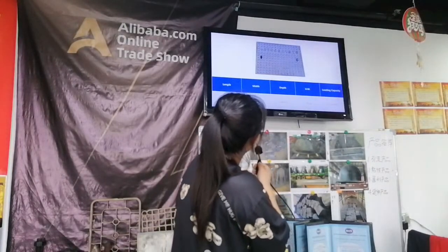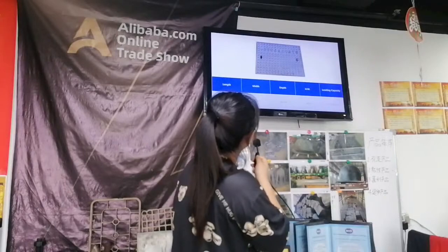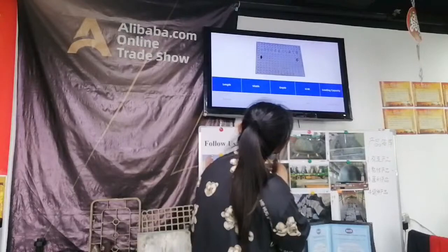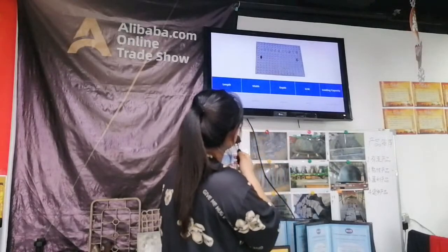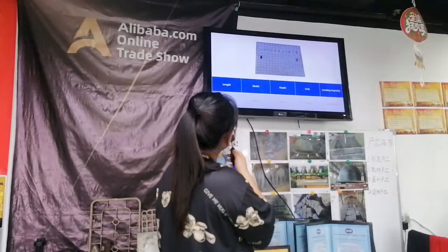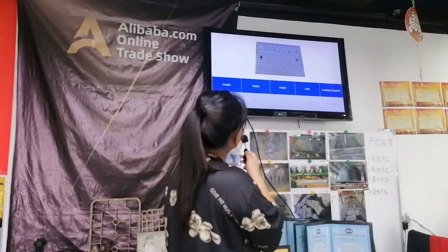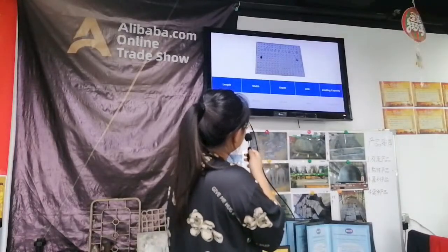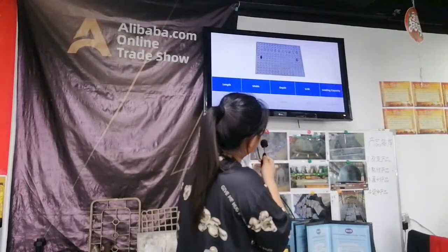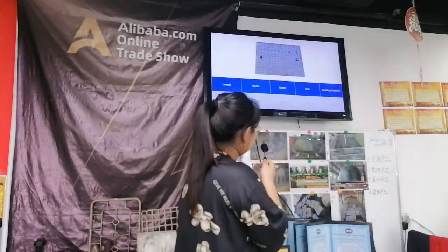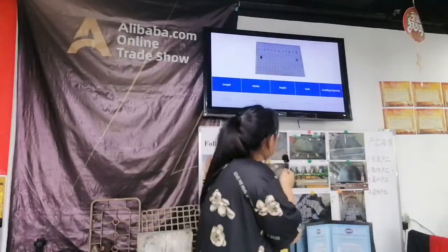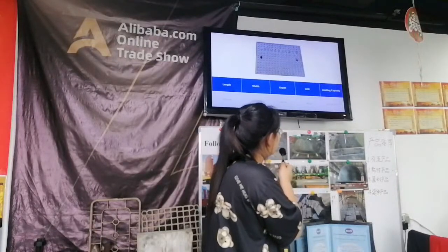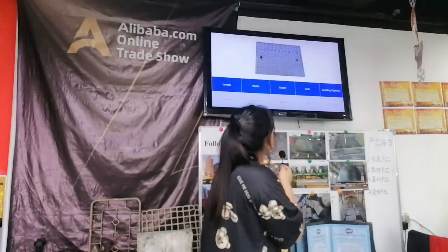This is a product made in our company. The length is 560 mm and width is 460 mm, the depth is 45 mm and unit weight is 30 kg. The loading capacity can be according to EN 124 F900.